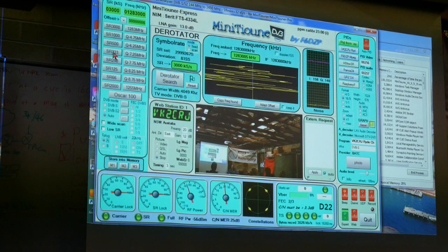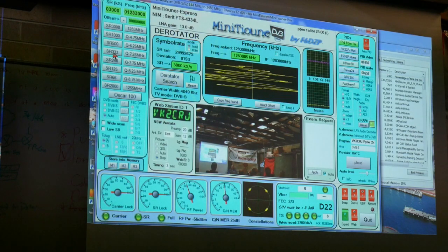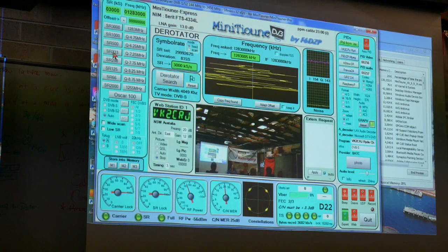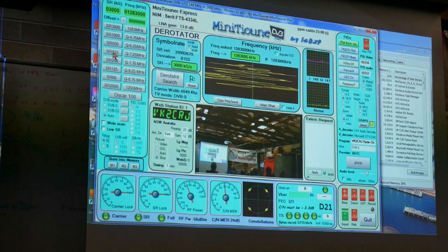Yeah, and so people are even going down to 50 megs now and transmitting this. But we've managed to get it to work on 70 cm. We thought about 50 megs. I haven't got any 50 meg equipment, and you might think, well, okay, it's a lower frequency, but then you need a much bigger antenna, and 6 metre beams aren't that uncommon.